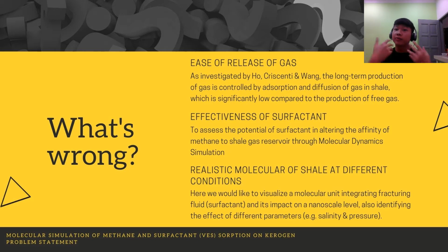As for the problem statement, the first point suggests that there is an issue when it comes to the ease of release of gas. Based on research, adsorbed and diffused gas holds up to about 20 to 85% of the gas stored in shale gas reservoir, while free gas accounts for only about 30 to 47%. So to produce more gas in the long term, there should be a focus on adsorbed and diffused gas, of which in our case, we are simulating the adsorbed gas.